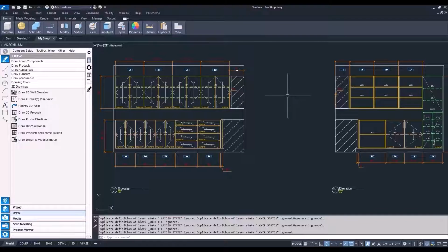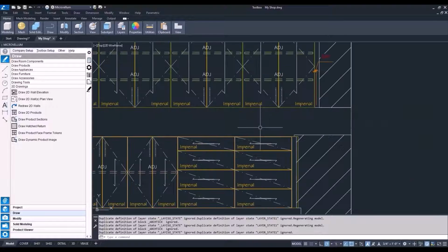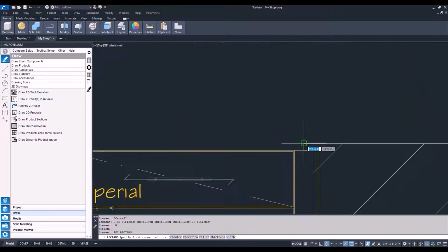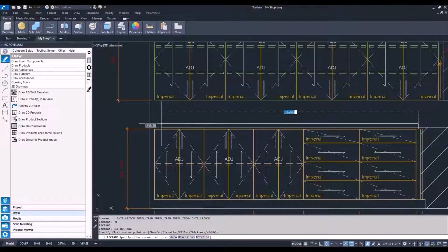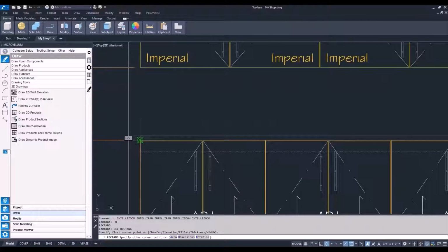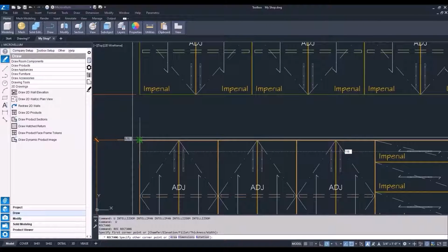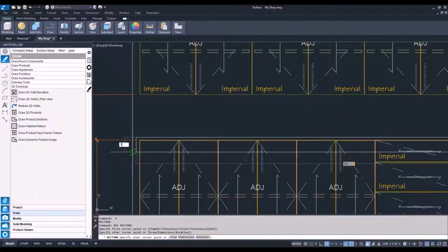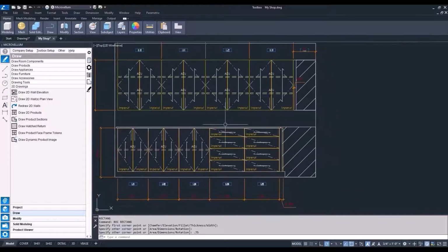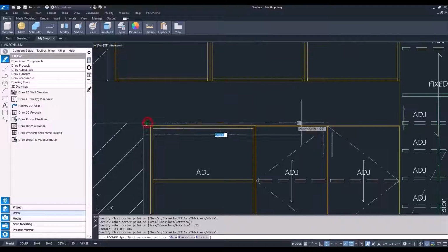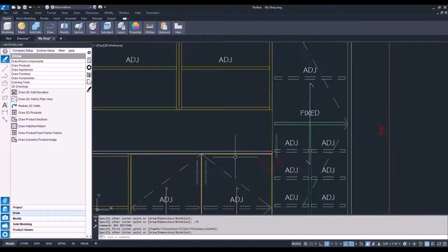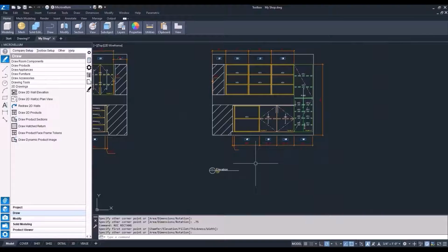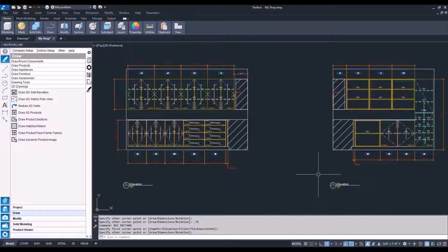And then this would be the point that you can use some of those AutoCAD skills that we've learned and start adding some rectangles or some other things that are representing countertops and toe kicks. The 117 is to the end of the cabinet. We'll add another inch, make it 118, hit tab, and 0.75 for the height. There's another rectangle to represent that countertop. We can do the same thing for our toe kicks if we want.